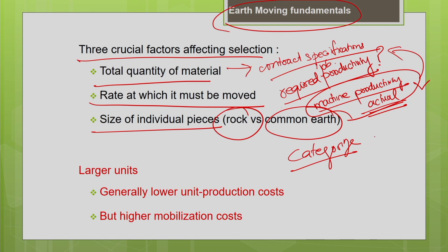Basically, you need to do some geotechnical investigations. Okay, you need to do some geotechnical tests or investigations to categorize the material, or you may even be supplied with the information by the contractor, or you may have to carry out some tests to know the type of material which you are going to handle. According to that you have to make the selection.